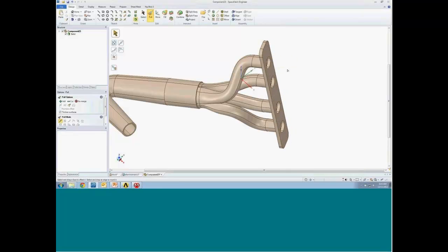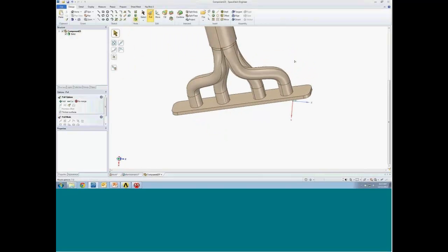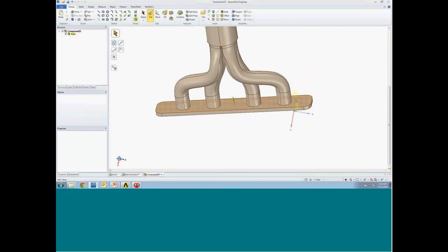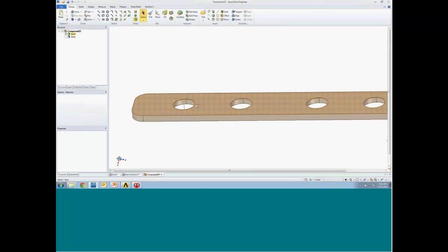Now maybe for the purposes of your mesh, you want to divide up this solid into a couple different pieces. Maybe along this face, you want to split it up. Well, it's 2 button clicks. Well, 1, I had to grab the face, and 2, I invoked that tool called Split Body, which breaks this up into separate bodies. So for sure, you're going to have some kind of a boundary condition where you need to identify the points along this face where the other body imprints on it.